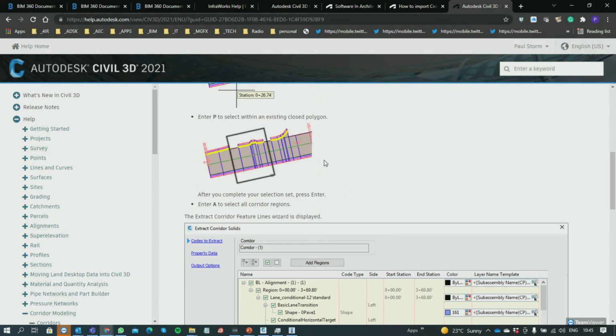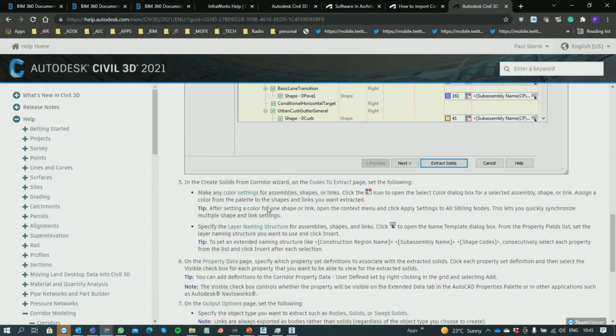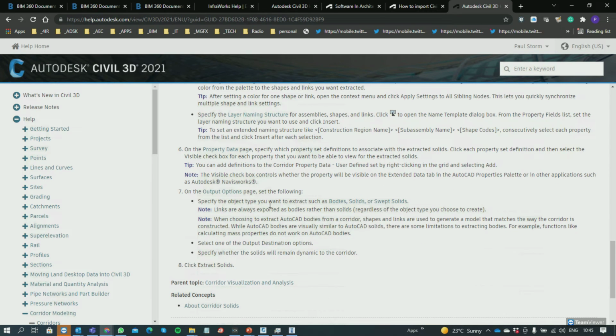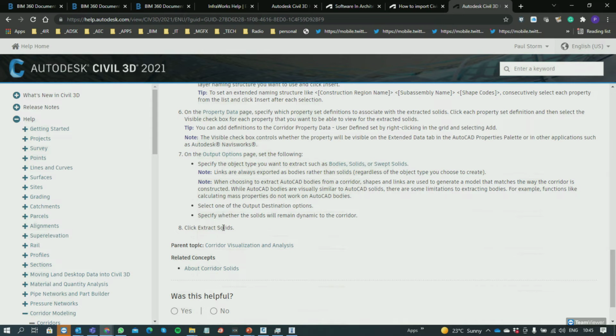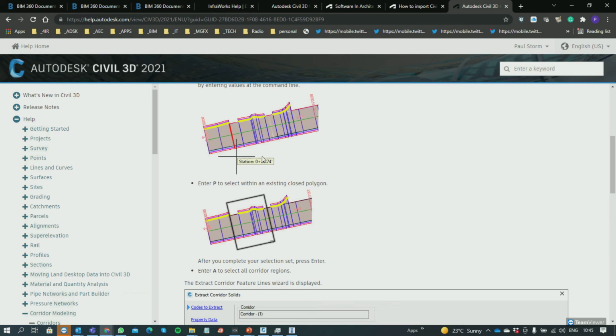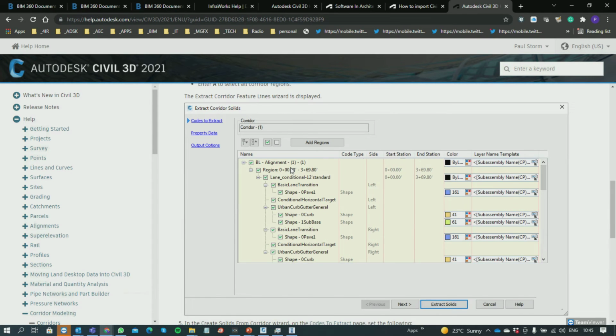And then after all of that is done and a specific region within the corridor is chosen, then you can write that out and once again link that as extracted solids into your Revit file. So it comes down to being AutoCAD files in which the Civil 3D geometry has been not exploded, but extracted as solids, and which are then brought into Revit. So some of the items that would play a role here, for instance, is